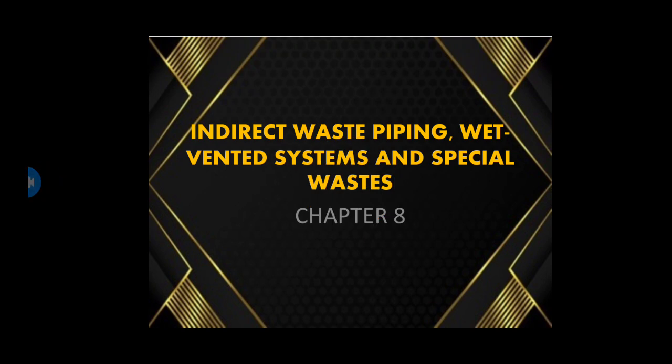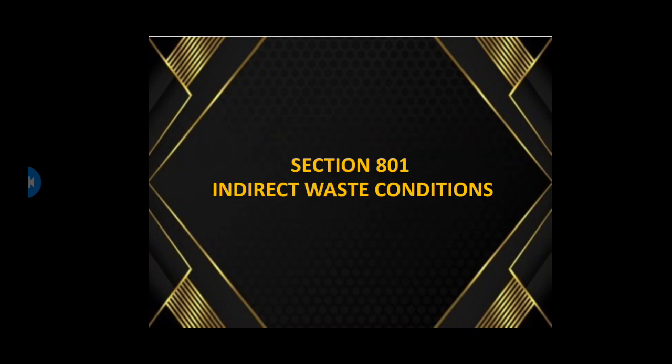National Plumbing Code of the Philippines, Chapter 8. Indirect waste piping, wet venting system, and special wastes. Section 801. Indirect waste condition. Indirect waste is a drainage piping that runs from plumbing fixtures or appliances and discharges into a separate waste pipe or receptacle.